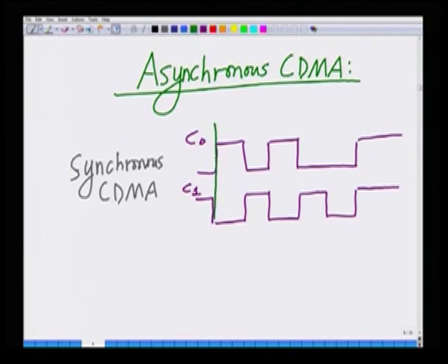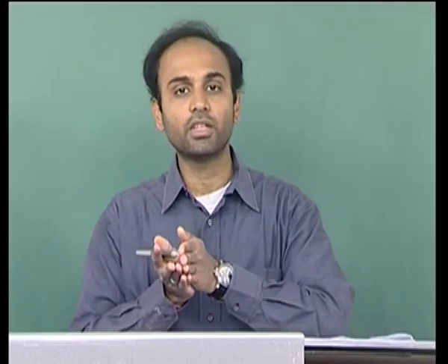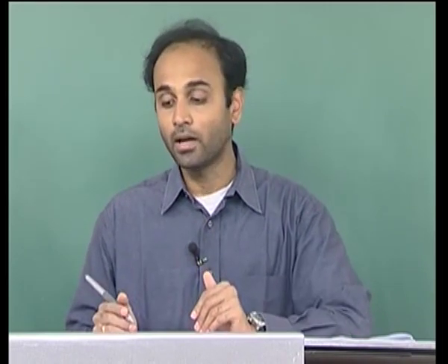I have the edges aligned. I have the CDMA code sequences aligned. What that means is the base station aligns this, multiplies the symbols, sums this up, and transmits them in the downlink.